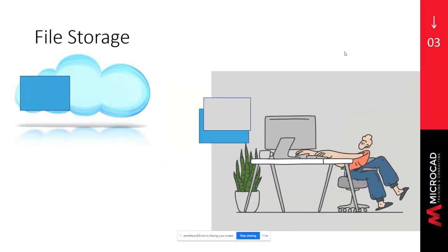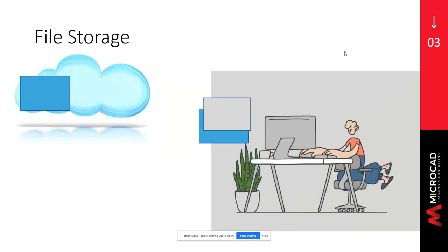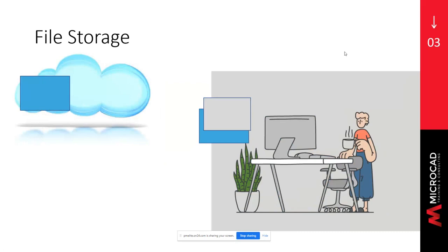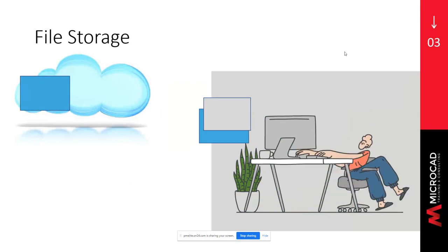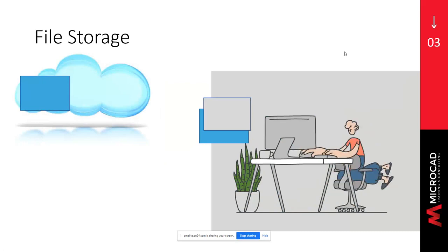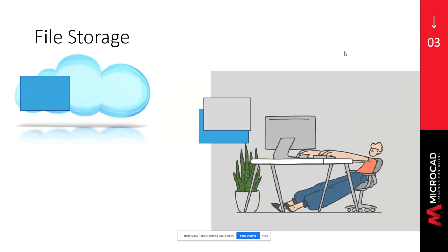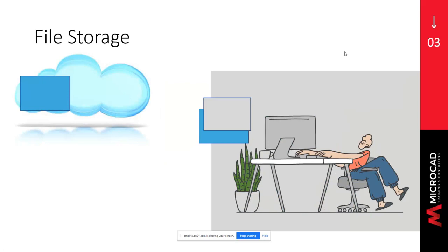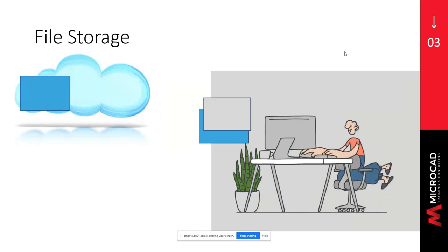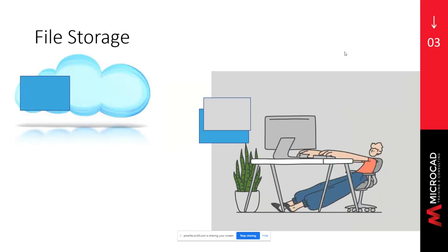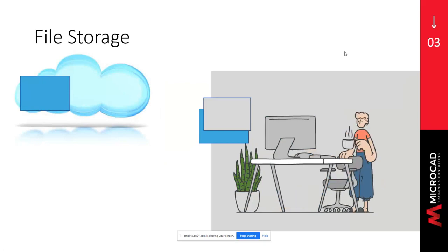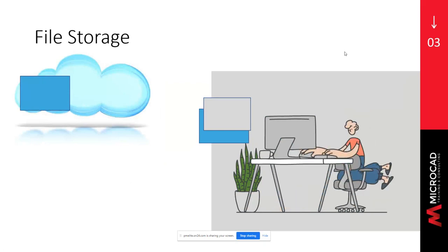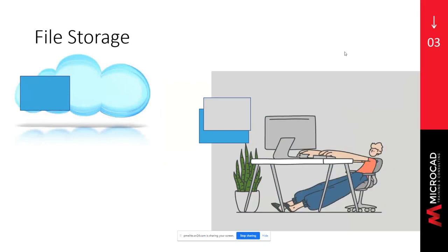In this technique, the users are exchanging files using the Autodesk Cloud, but not really taking advantage of any of the collaborative services. Jeff, the MEP designer, has a file shown in blue from Oscar that he uses as a background. He downloaded it from the cloud onto his workstation. Jeff's Revit model, shown in gray, is linked to Oscar's model so Jeff can design the mechanicals referencing the architectural elements. These files are all on Jeff's computer.